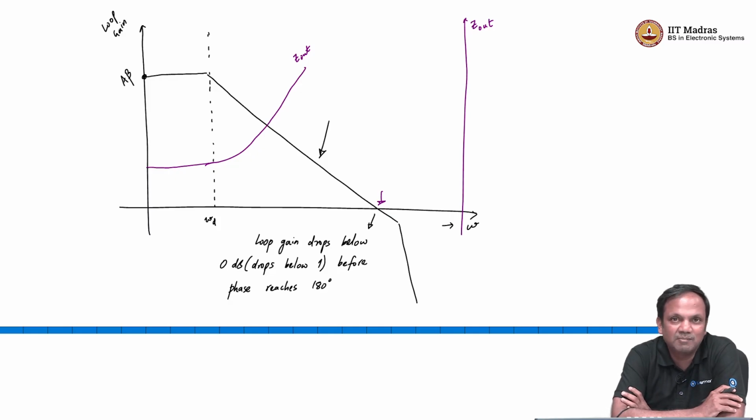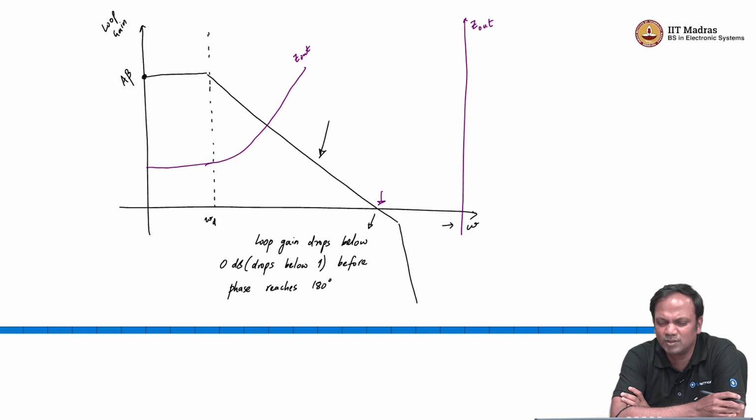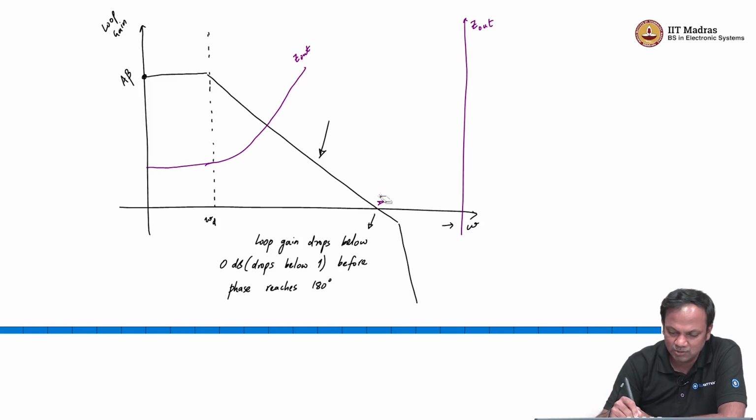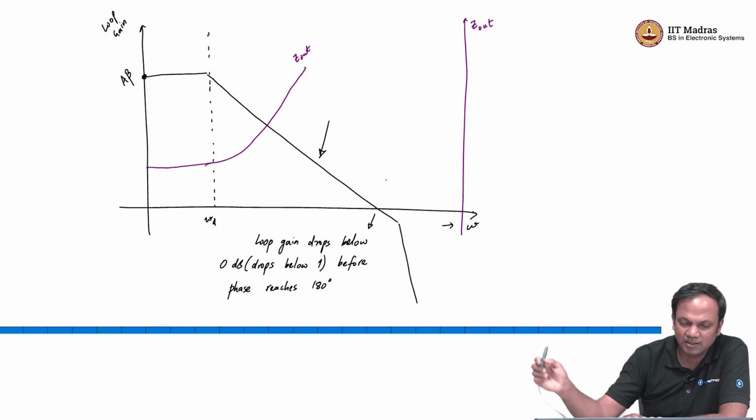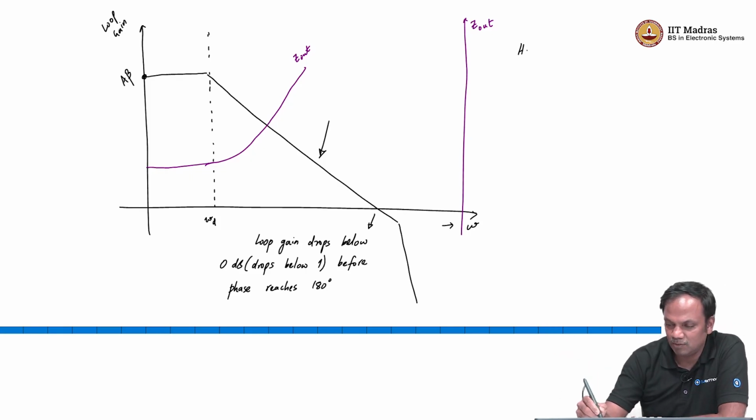At DC is okay, but my load current has a certain frequency nature to it, and what will happen to the performance at those frequencies? Because if the output impedance is very high, then I am going to get a lot of voltage drop at that frequency, and that is going to have its own associated problems, right.